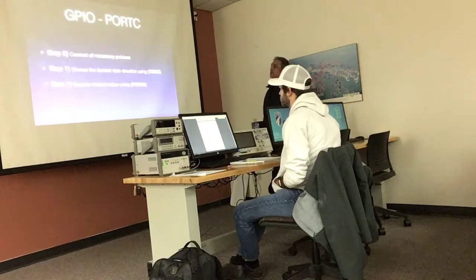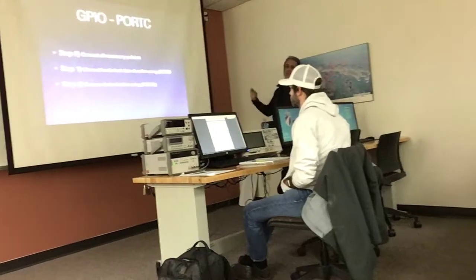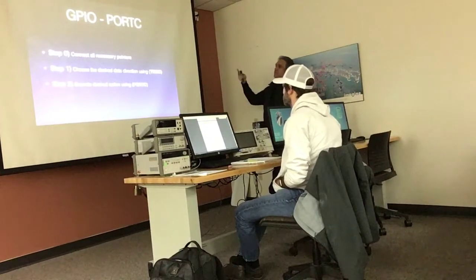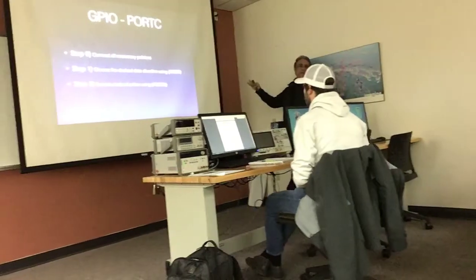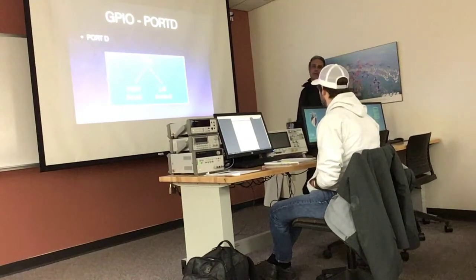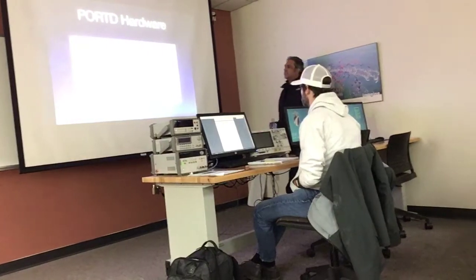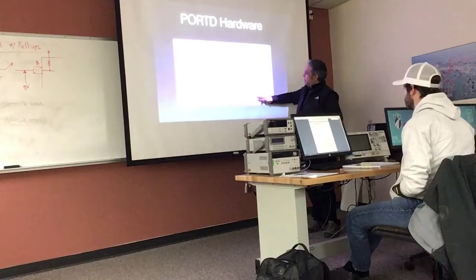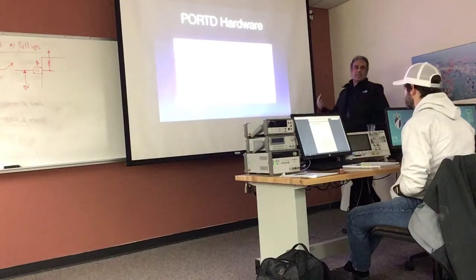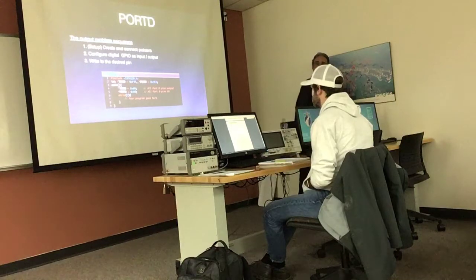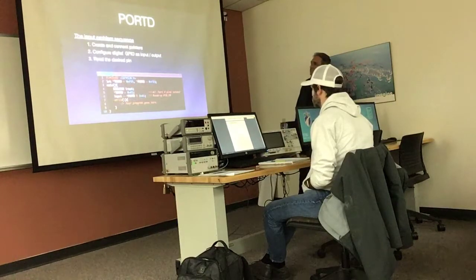Port D, that is the recipe. Only 3 steps. Set up the pointers, make it input versus output, and then whatever you want to do with it. And here is port D, no analog. Port D is actually split here and there. So if you notice, those guys have no analog. So same thing, same circuit. See it? All the same.